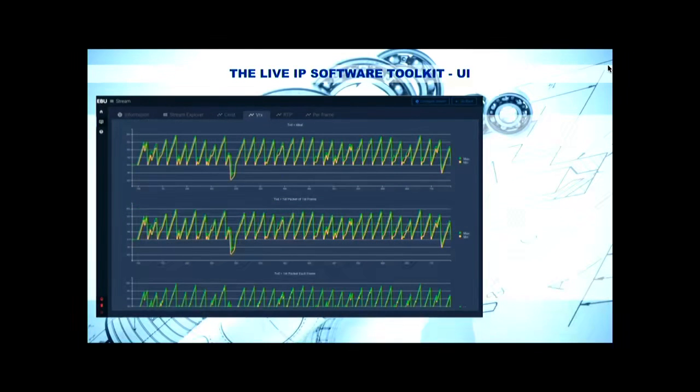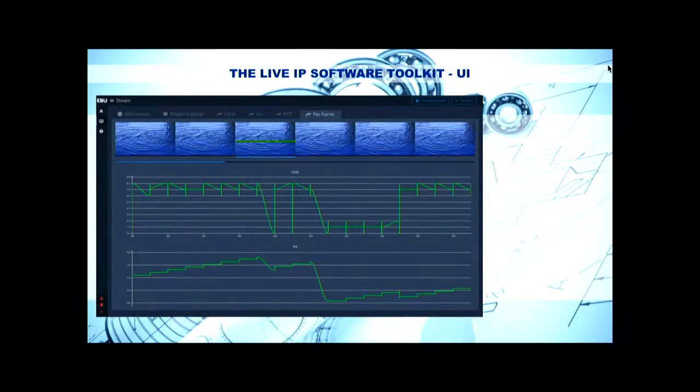Let's see if I have a nice one. This is a nice example of another one. This is the virtual receive buffer, and this is a tcpdump we got. And the guys didn't know why their solution was breaking, but actually it's very, very simple because you have underruns. There are no packets in the buffer when the application needs to read the video frames according to the PTP clock. So those are the VRX underruns, and actually we can run through frame by frame and see exactly what happened on this frame. You see the typical green line. There's no data available to reproduce the picture.